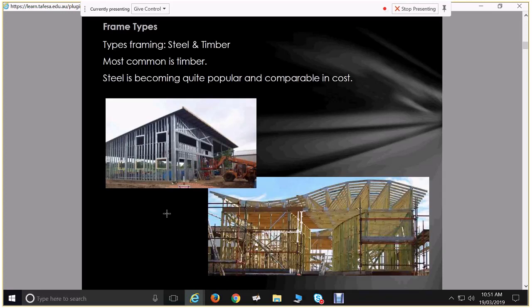So that's why we would use steel framing, because it's all done in the factory, and when it's all done really efficiently like that, it can be done much cheaper. That's why we would use steel. The reason we'd use timber is because we can have more control over that. Mostly when we talk about buildings and building decisions, it comes back to economics. Sometimes it comes back to client preference or other considerations.